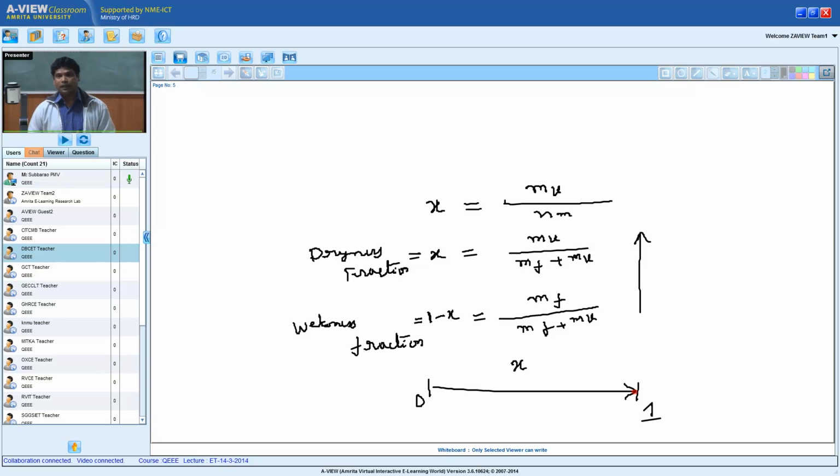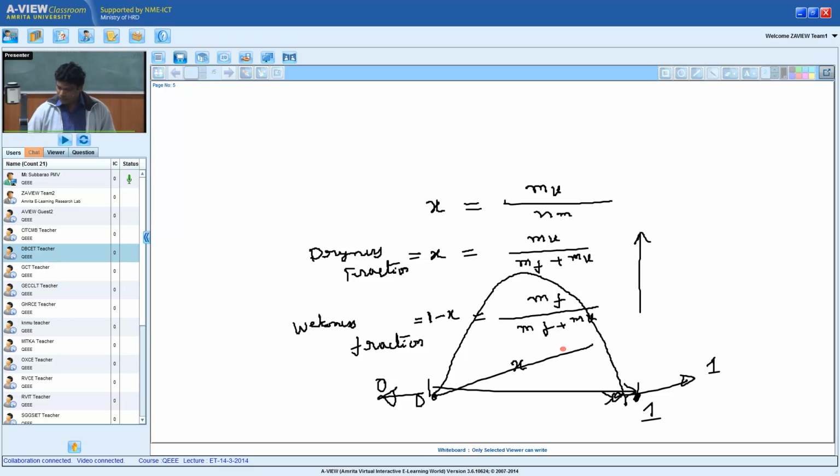Very important. Let us say I am trying to draw the dome above this particular one. Sorry, this is the one. Now, if I draw the dome, x has no meaning on this side, and x has no meaning on this side. If somebody still counts, x remains 0 here, x remains 1 here, and x varies from 0 to 1 in this particular range. So that's how the dryness fraction works, and most books say it because of the engineering consequences, which I will tell you later.